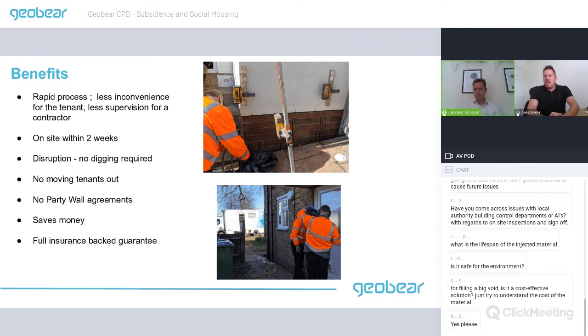Yeah, James, just to add, that's a question we get asked a lot, and there's a paper coming out. I think it should be in October, where we've had some live trials, and an independent consultant company has tested and verified our materials in clay. Going back to the former licensees in the UK, they typically avoided clay, and they were based in the northwest of England, where it wasn't as prevalent. So historically, they could have probably treated clay, but for whatever reason they didn't. But this is something, high plasticity clays. Obviously, it's a case by case basis, but under 40 PI, then this is.